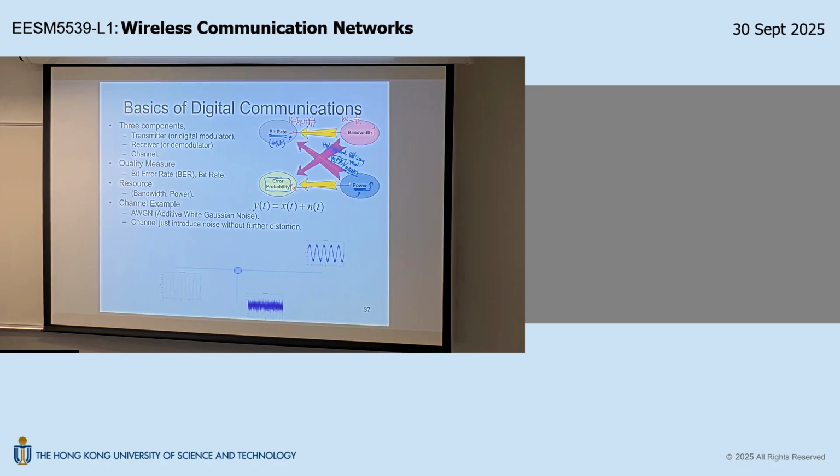Having a large signal-to-noise ratio is just a matter of your power amplifier dimensioning. You just need to make sure you have a sufficiently large power amplifier so that you have a sufficiently large transmit power. Then the signal-to-noise ratio of your distribution network can be controlled to any level you like. So for this noise-limited system, achieving signal-to-noise ratio to a target level is not a big issue. Therefore, you can usually afford to use very high constellation order, like 4096 QAM.